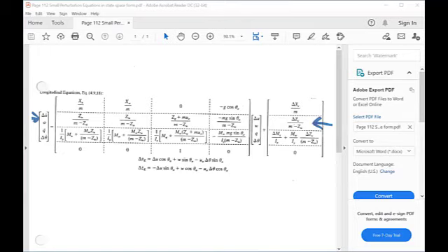And at this point, you're thinking, what a giant mess, right? A lot of equations, a lot of terms to keep track of. But inside all those terms are just the wing area, the horizontal tail area, all of the geometry parameters of the airplane and the lift curve slopes and all that stuff. So it's really just stuff we already know how to estimate. You just crunch the numbers, and then inside the matrix, you just get a number everywhere. So you calculate it.